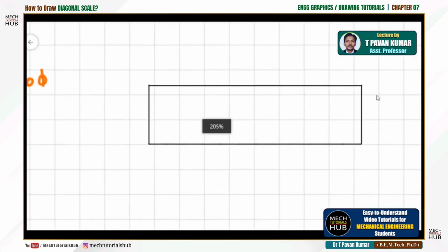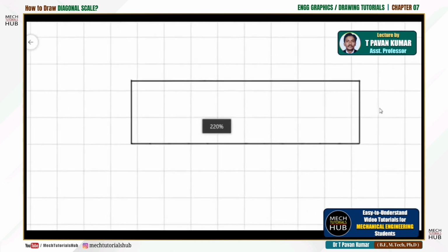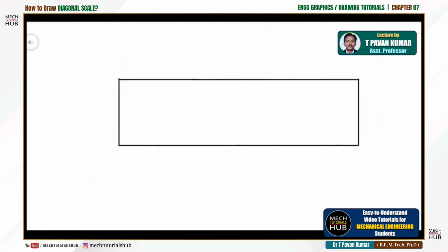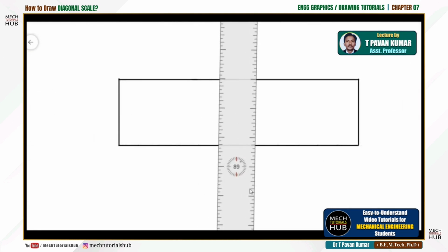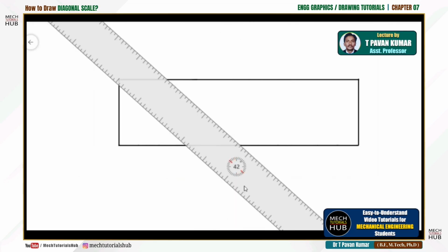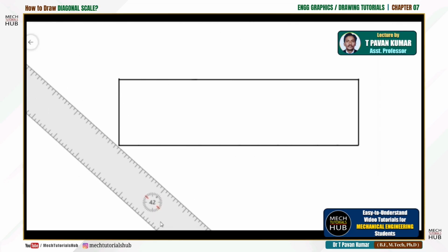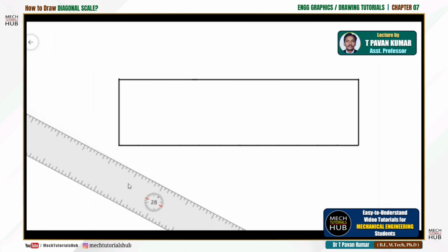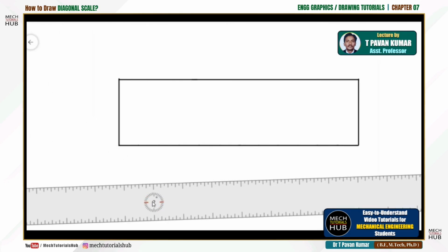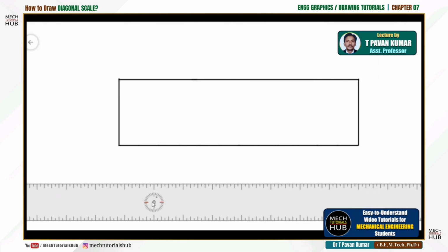That is my idea. Now, by considering 12 centimeters, I have drawn a horizontal, and a vertical is drawn by considering 5 centimeters as the height. Now we need to divide the length of 12 centimeters into 6 different parts. That can be done simply by saying 12 divided by 6, but fractions can't be read through the scale, so we can divide by using the line division method.